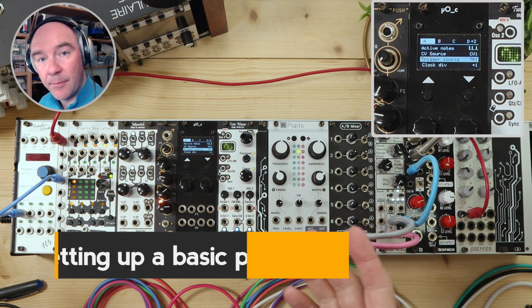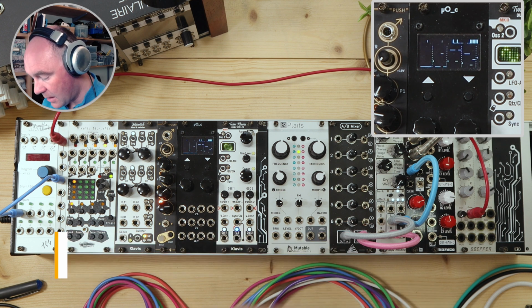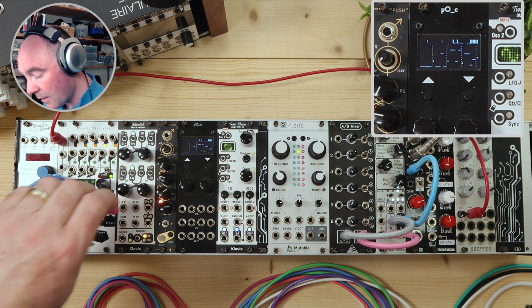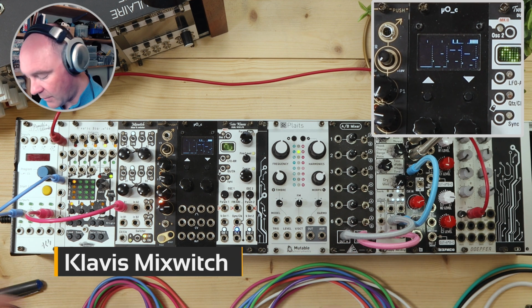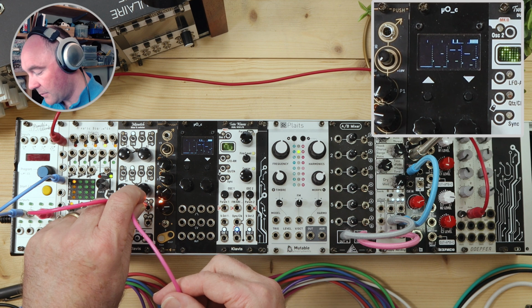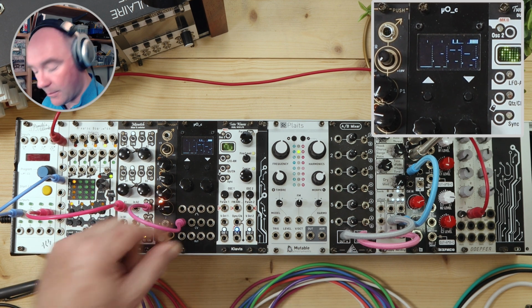Now let's connect up the output of Pam's new workout. I have an LFO here on output 4, which is just a sine wave that'll just cycle along. I'm going to attenuate it slightly because the output range is quite high. From 0 to 5 volts would be just crazy noisy. So we're going to attenuate it via the attenuator here in Mix Switch. Take the output of that into quantiser A, CV1 input.